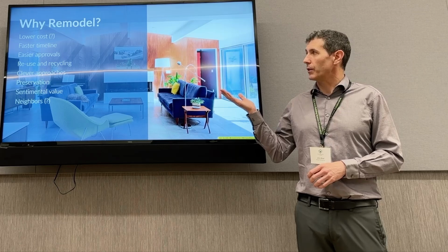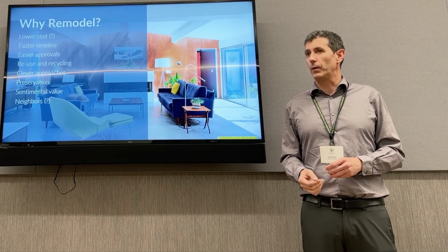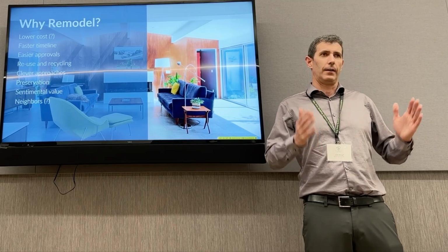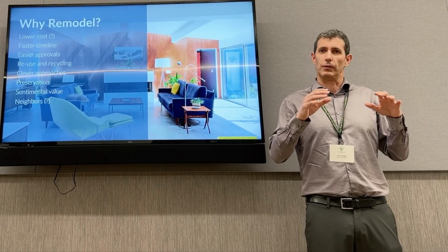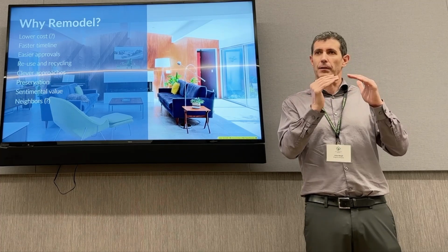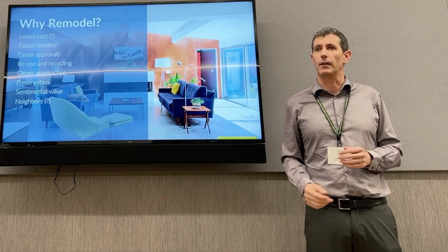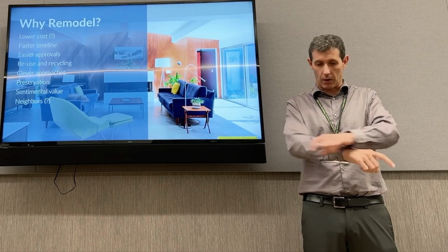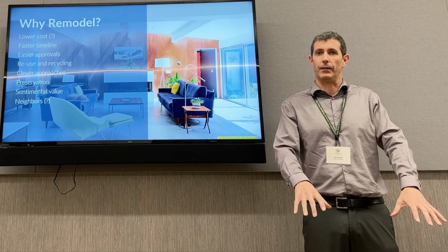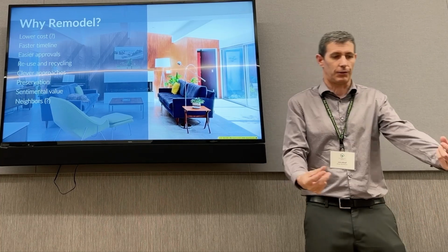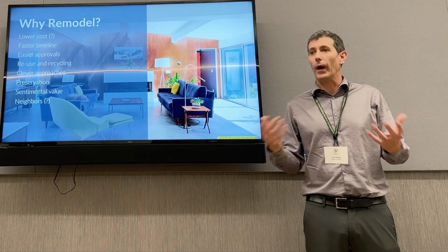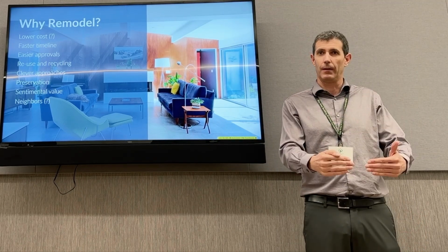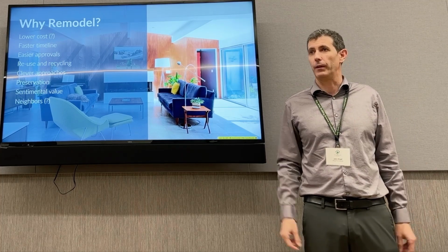The next one is reuse and recycling. And we think of, and what Dave's last slide maybe showed was the reuse building, right? Which was, they gutted out and left in place all the framing and the concrete. So when you do that, you're reusing all that concrete. There's no new embodied energy for that, or you're underpinning it in certain locations. Well, that's still way less than stripping it out and pouring a whole new mat slab, or putting in deep piers, or putting in deep perimeter footing.